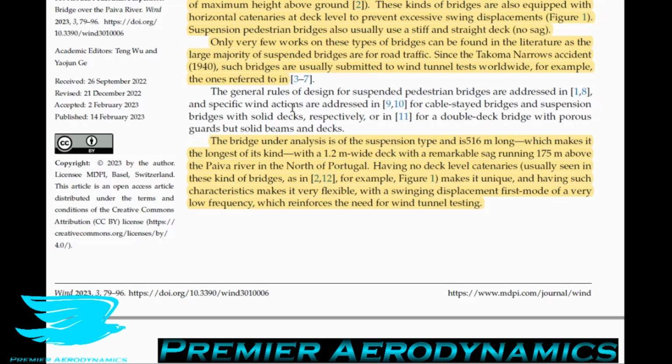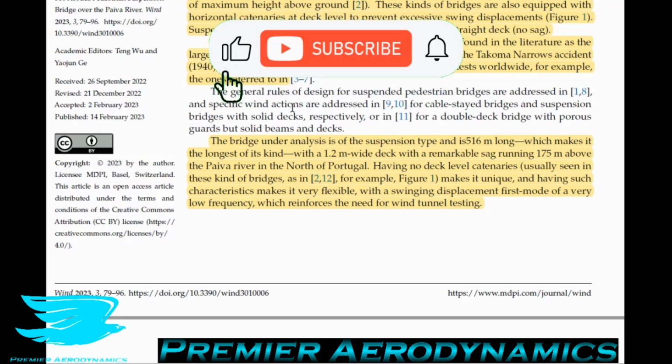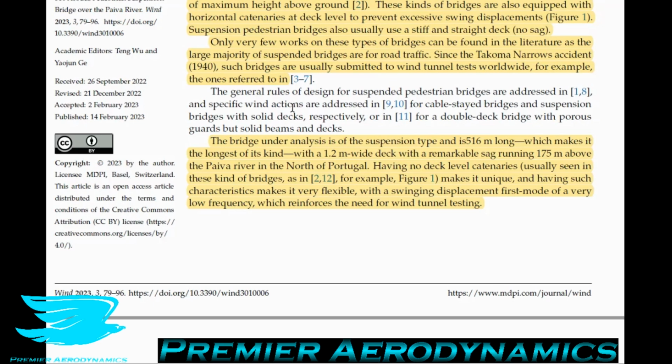they didn't know why this was happening, and all these engineers were trying to figure out why, but the old girl kept her secrets. And then finally, one day, an engineer realized that it probably had something to do with the natural frequency of the bridge and the aerodynamics, with the wind that was present exciting that natural frequency. We'll get into these instabilities in a little bit, but for this bridge, the wind was going over it and producing some flexing, which then started to amplify because the oscillation frequency matched the natural frequency of the bridge. So this coupled and just got worse and worse until it disintegrated.